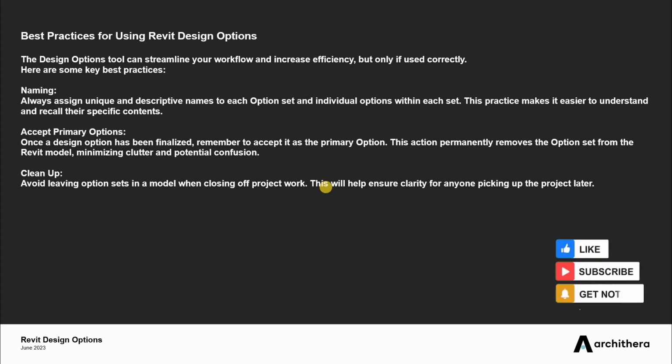And also, when you're moving on from a project, if you work in an office where projects are recurring, maybe you're done with a project, and in 2 years time the client asks you to do some more alterations. If, say, you've left the office, or even if in 2 years time you have to work on the same thing, you need to be sure of what the final model is. So you need to make sure you clean your option sets out.